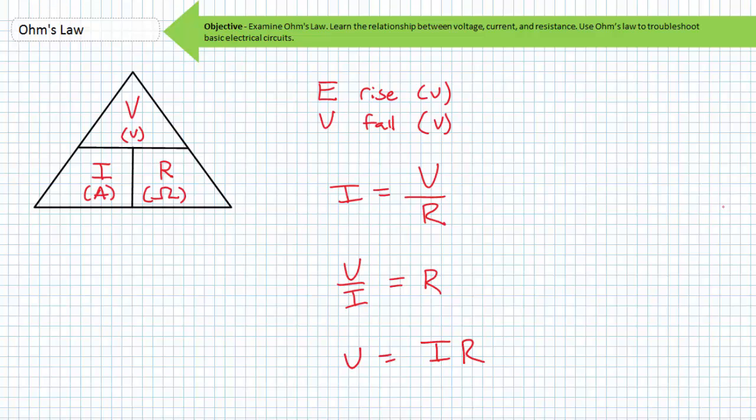I know this might be a new, weird, and unwieldy concept to you today, but in the upcoming days, weeks, months, and years of use, this is going to become something I expect you to use without a sign of hesitation. It should be a natural reaction and immediately evident that if you decrease resistance and have a high supply voltage, your current should be high. It should be totally obvious to you if you are supplying high voltage and observing a very small amount of current, the resistance must be incredibly high. And it should be readily apparent if you're observing very little current and a very small resistor, the voltage drop across it will also be exceptionally low.